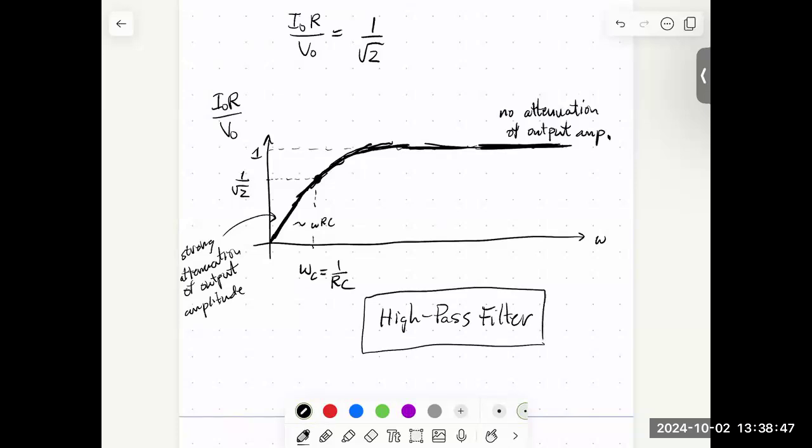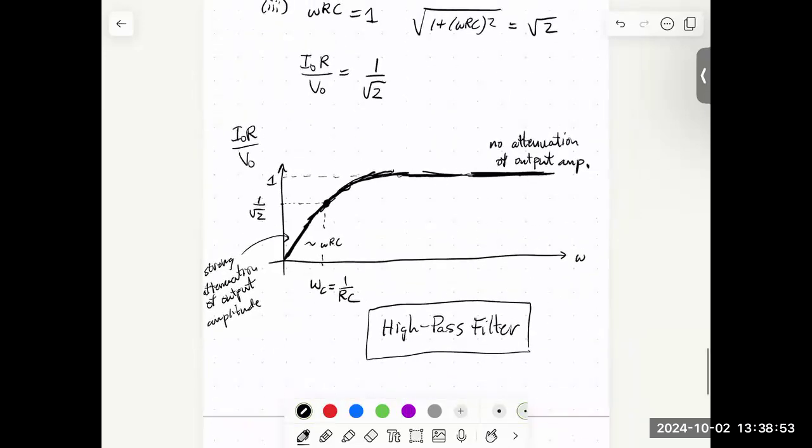So if you wanted to make a low pass filter, what might you do? What could you do differently? We're measuring right now, we've measured the output across our resistor. If we have no voltage dropped across our resistor, where is all the voltage? If we're at low frequency, we have an RC circuit, our resistor has very low amplitude. Where's all the amplitude?